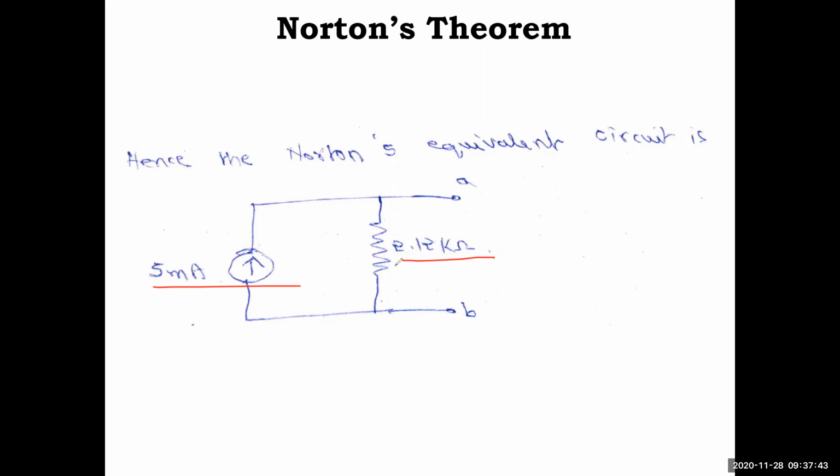So fine, now what we have to do? In the previous two problems, we stopped over here, right? Now they have told you to find out the I naught current. That means there is a 2 kilo ohm load. We have to connect it back, and you have to measure the current across this branch. Which will be very simple, you can solve it with the current divider rule. That part we will take up next. Hope you have noted down this.